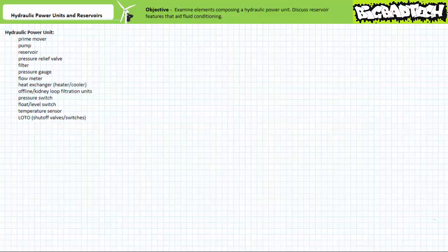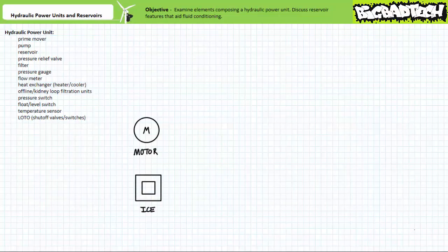You're probably familiar with most of these elements already, but since they perform essential roles, let's do a brief review. A prime mover is either an electric motor or gas-powered internal combustion engine whose responsibility is to convert one form of input, electricity in the case of a motor, and chemical energy in the case of an internal combustion engine, into rotational mechanical output. Rotational mechanical output is characterized by a rotational speed, often measured in units of RPM, and a twisting force known as torque, often measured in units of Newton meters or foot-pounds force.